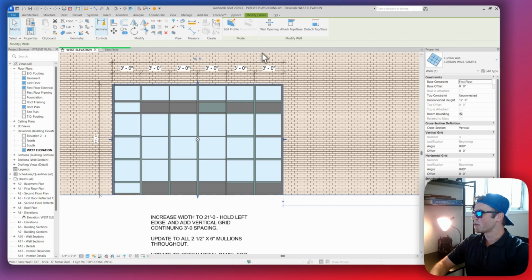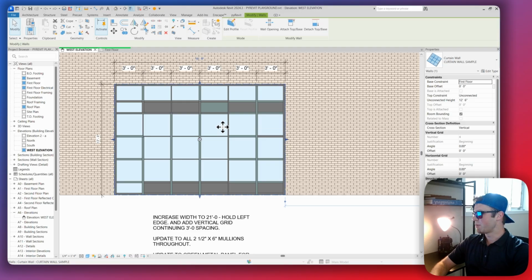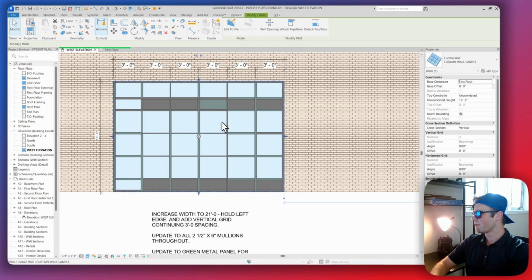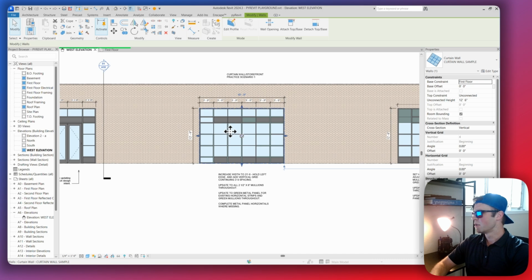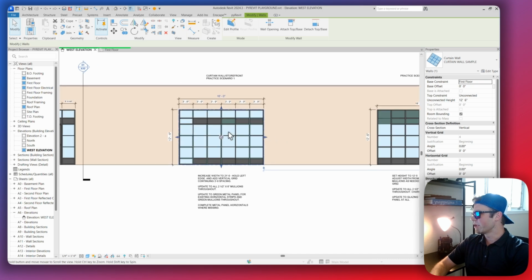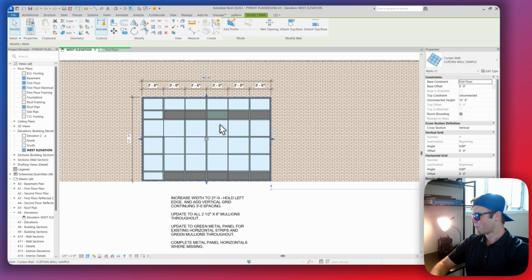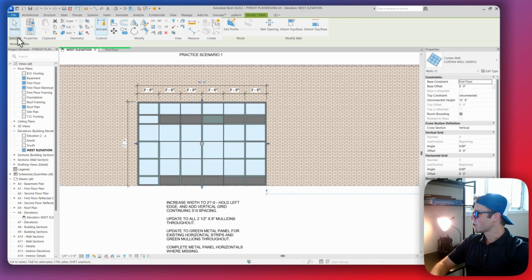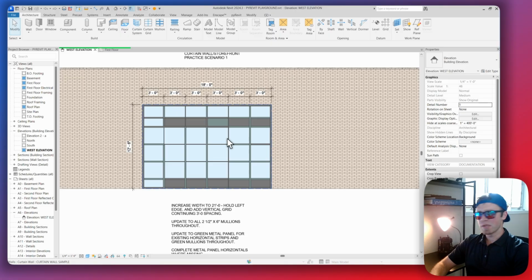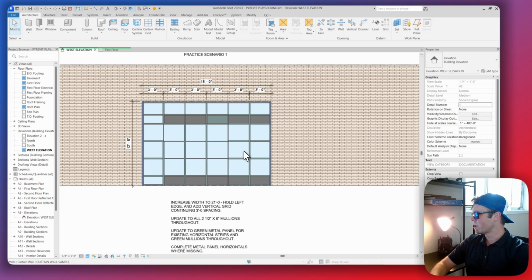You have the curtain wall selected when the modify tab is up top, and you're seeing the shape handles of the curtain wall itself. So that's just a little tip and trick I like to use when modifying curtain walls. It just saves me time and really just energy. It just gets annoying trying to tab onto curtain walls sometimes. So like I said, I have that on for the extent of this tutorial, and let's get going.